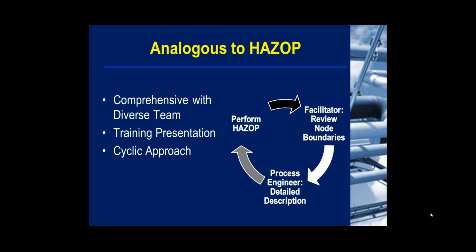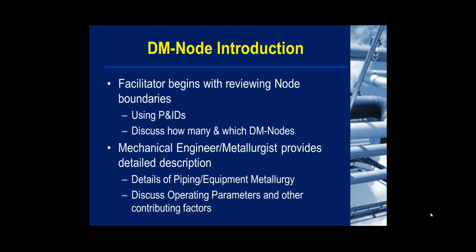So your final preparation steps after your full damage mechanism node list is developed is to compile industry literature and use it as a cross-reference. API RP 571, which is what Steve mentioned a little bit earlier, has a lot of good information as far as the detail as to how damage mechanisms propagate, and quantitative data, like for example here, this is a Nelson curve for HTHA.